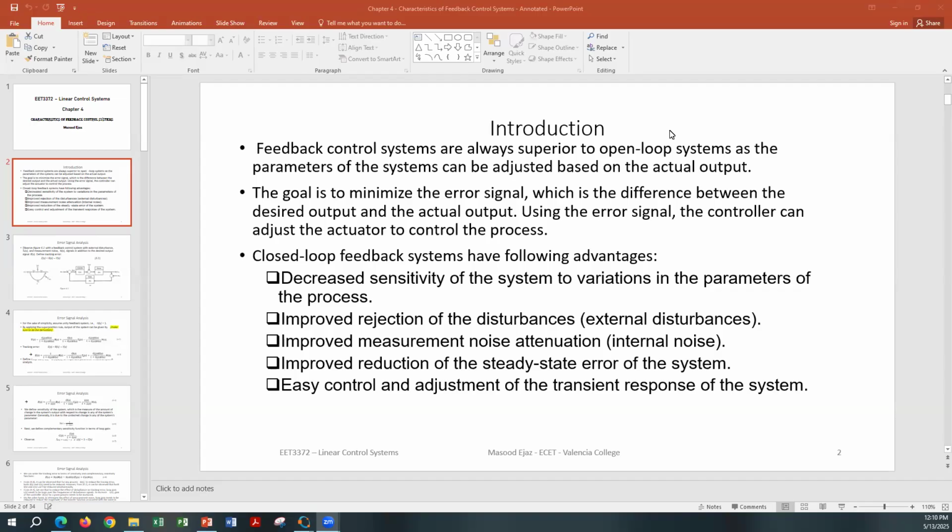Again, if there's a steady state error, that is, let's say the input is a unit step and the output steady state is 0.5. So now you have an error of 0.5, because the input value was 1 and the output value is 0.5 at steady state. So the difference is 0.5. That's a steady state error. It is the difference between the input steady state value minus the output steady state value.